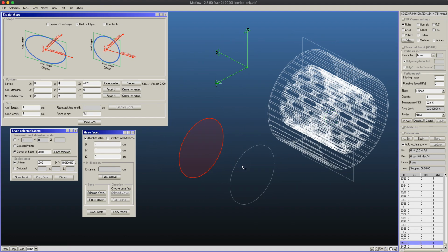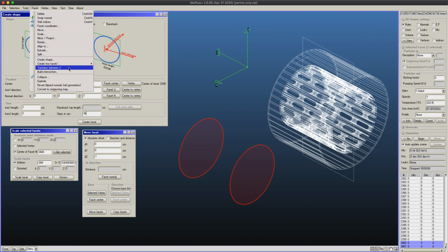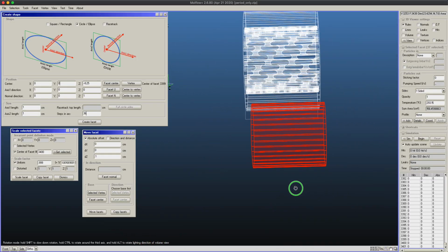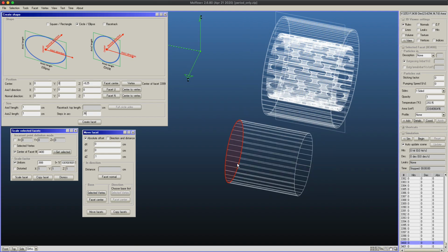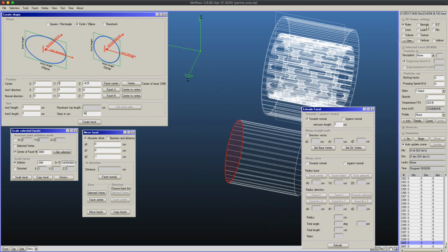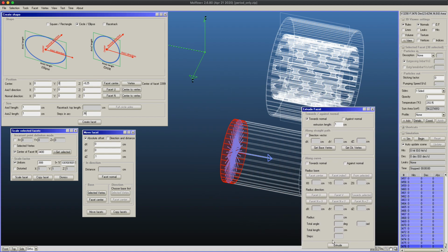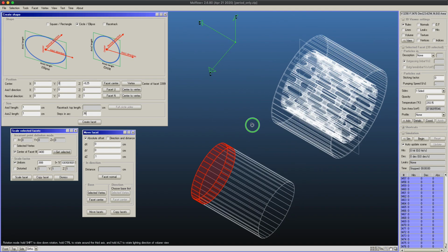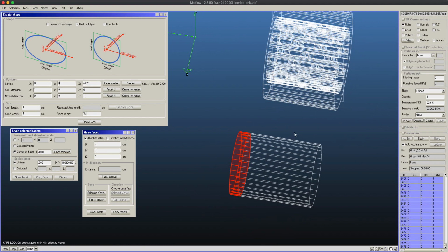Let's connect them. I will just use this transition between the two, and it automatically completes. So now I've got a cylinder. Apart from that, there is another command called extrude. If you know how long it should be, you can make an extrusion and then you can construct a pipe anyway. Now, since it's not exactly the same position, it's very easy to make selections. I can just remove the side caps. I will just delete them.